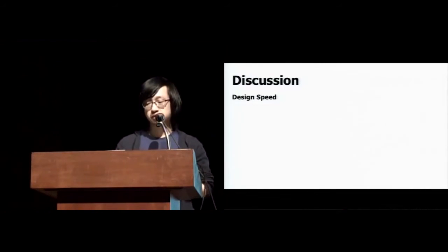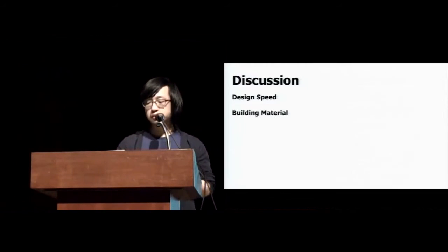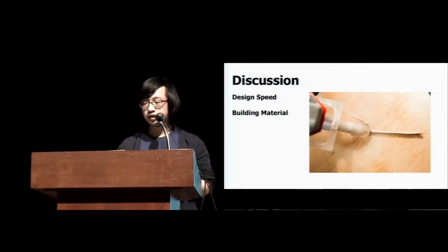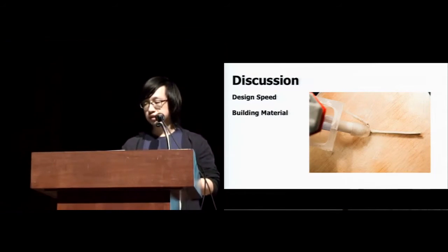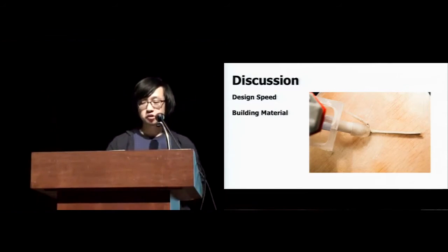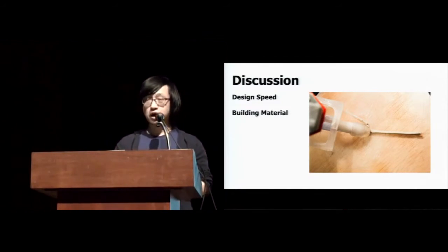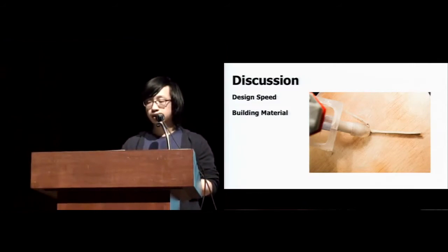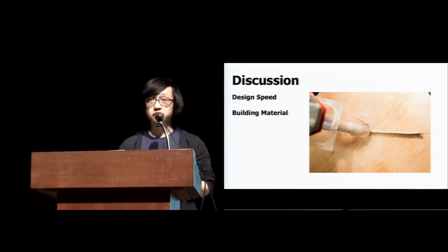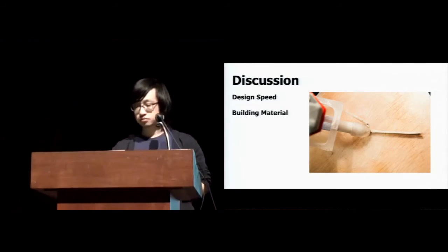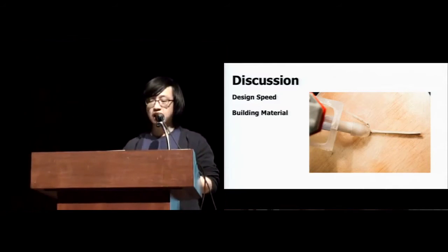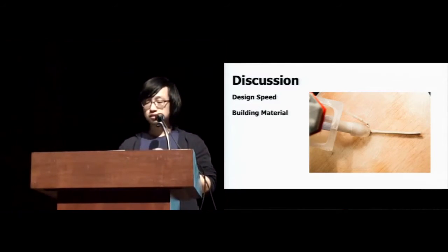Next, we would like to talk about the material. Drawing inspiration mainly from clay coiling, our exploration actually started with extruding clay. However, during our preliminary tests, we discovered that clay ribbon is too easy to break and takes too long to dry. We also considered plastic wires like ABS or PLA, but they also pose challenges for cutting because they are fairly rigid after they get cured. We finally opted for wax wire because of its low melting point, fast cooling, and ease of cutting.